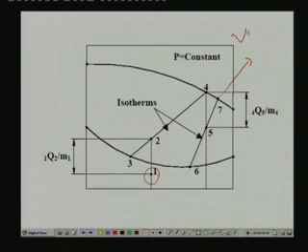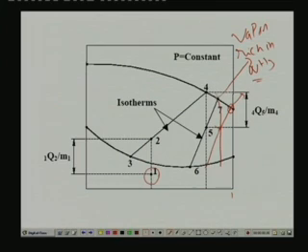Okay, we have taken subcooled liquid at this point and we are getting a vapor that is rich in ammonia. Suppose this process is continued further. You will find that you have taken this vapor and again cooled it, and you have separated out the liquid and vapor again. So, you can see that this point, that means the outlet point, progressively moves closer to the pure ammonia state. That means you are getting vapor that is rich in ammonia at the exit of this arrangement. That means the whole system is working like a rectification column.